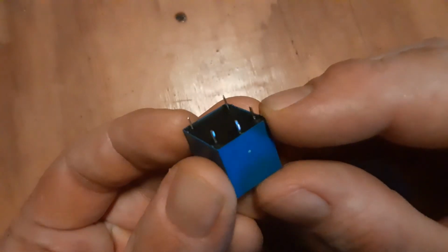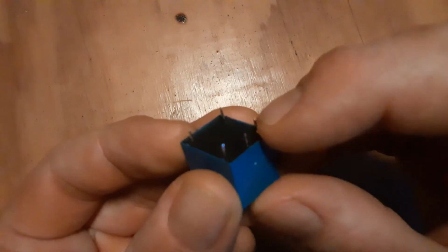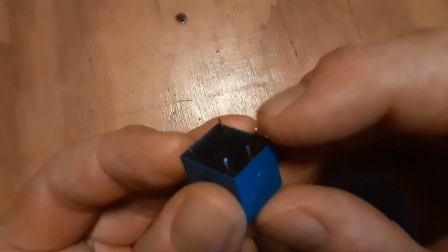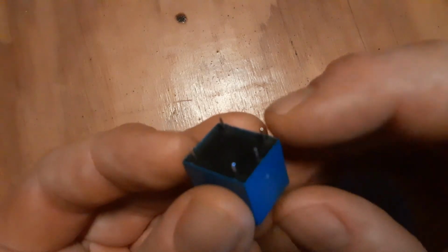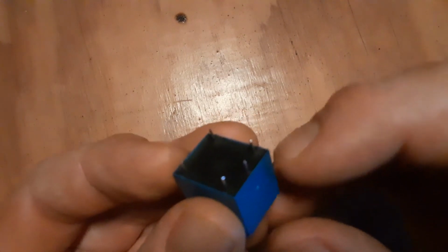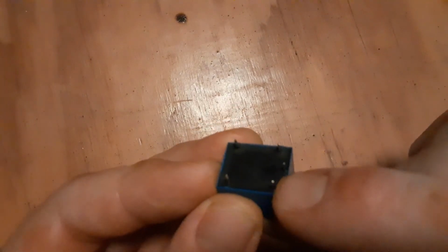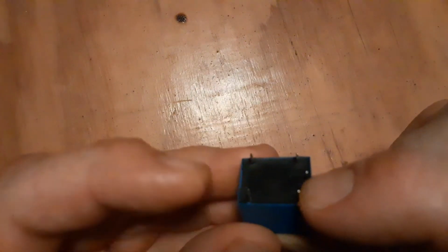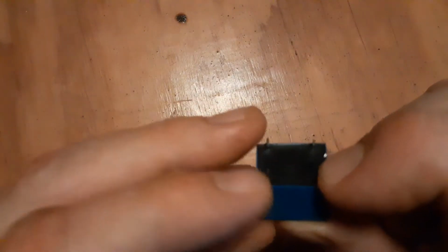And let's see this corner. So on the bottom we have 5 pins. So these two, those are our coils. So we'll bring a small current in there, such as from a microcontroller. And when we apply a current, as it flows between those two, on the inside here, it runs through a coil like out on the board and creates a magnetic field. This one over here will send outputs to these two. So we bring our electricity in over here, and then it's going to come out these two.